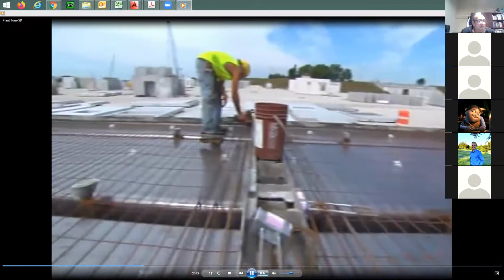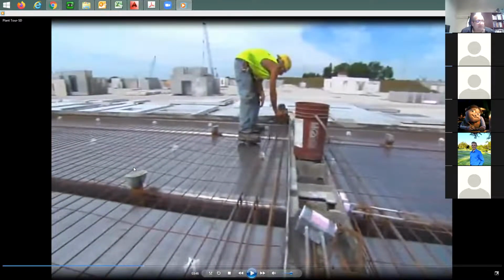After the strands of this double T are stressed, you also have this mesh that you put on the top. It's going to be a very light, welded mesh, so it comes pre-welded. Otherwise, it would take forever to lay the rebars and tie them to each other.